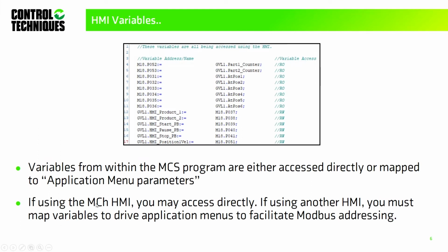Now the advantage to using our HMI is the fact that it's manufactured by XOR, we don't make it, it's private labeled, but what XOR have done is they've gone in and they have modified the communication driver for Modbus TCP IP to include all of our menus and parameters. So you can access things directly by menu and parameter, and you'll see that here in just a little bit.